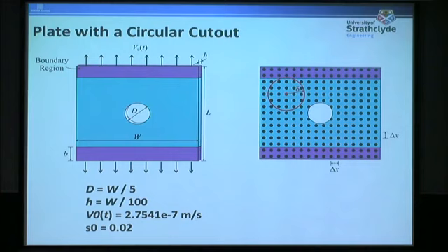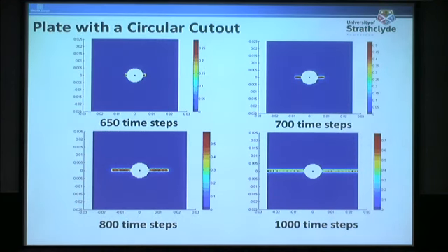So now we would like to see if Peridynamics can also find out the damage initiation. If you look here, since we are pulling at the top and bottom, we know we should have stress concentrations right there. Again, Peridynamics did a good job in finding out the critical location by itself. We didn't tell the simulation to start damage initiation from here, but instead it just does this automatically. And later on, the damage starts propagating to the left and right.